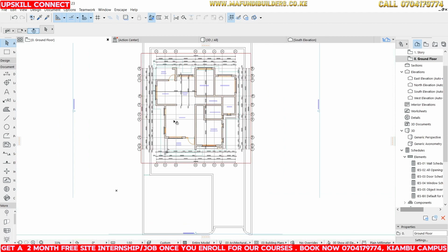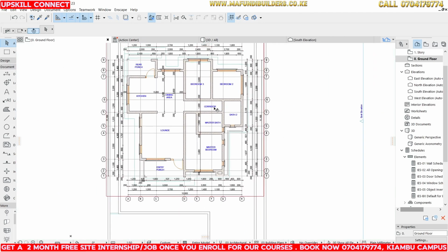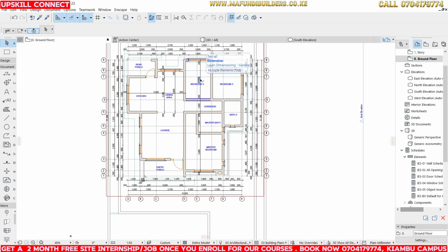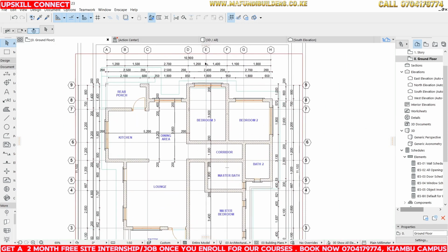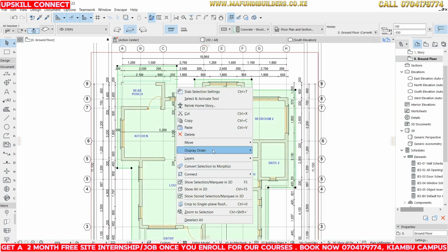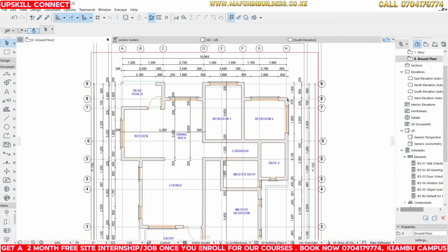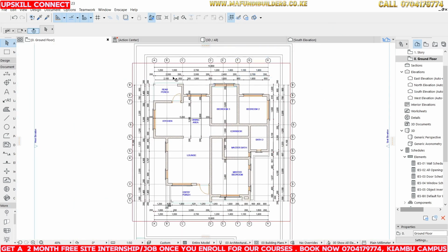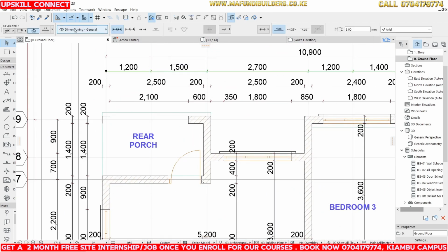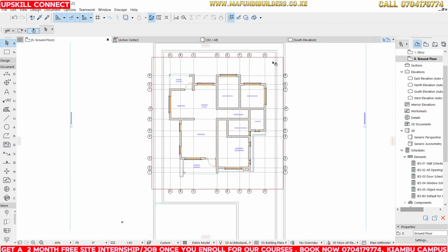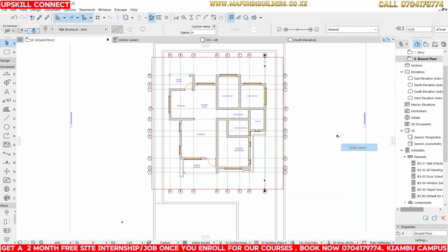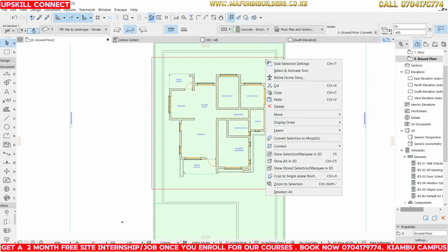But guys, remember that these dimensions might change depending on the layout that you want, right? So we're going to have different layers of dimensions. This will be the primary measurement, but then you're going to have, for example, when you're having the setting, the site plan, another layer of dimensions. So these dimensions are in dimension general. You can also hide them if you want to hide that layer. Yeah, so all the dimensions you see. The grid lines are also in their own layer. Now you can hide them, like that. And just the same way, you can hide all these things.